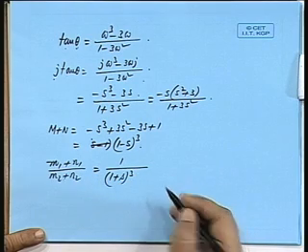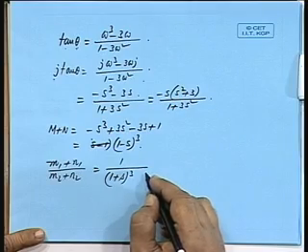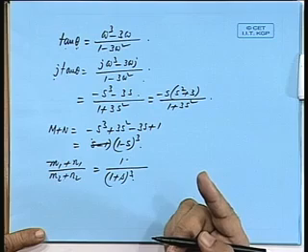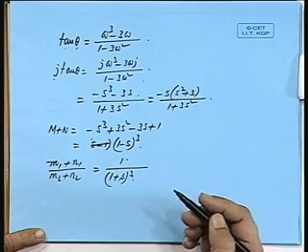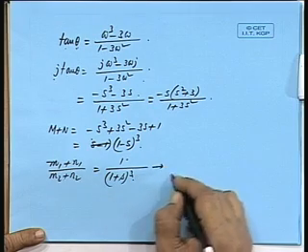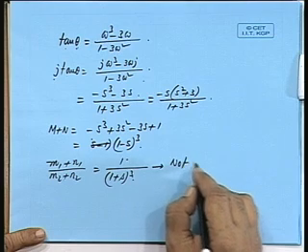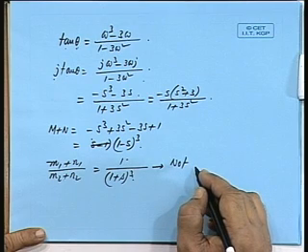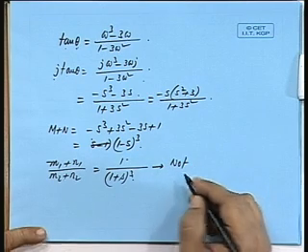Is that all right? So, this is not a driving point impedance, it is an impedance function, a transfer impedance function. In case of a transfer impedance function, you may have a difference in the degree of more than 1, but in case of a driving point impedance or admittance function, we know the difference in the degree should be restricted to 1. Here you can have more than 1. So, this is not a driving point function.